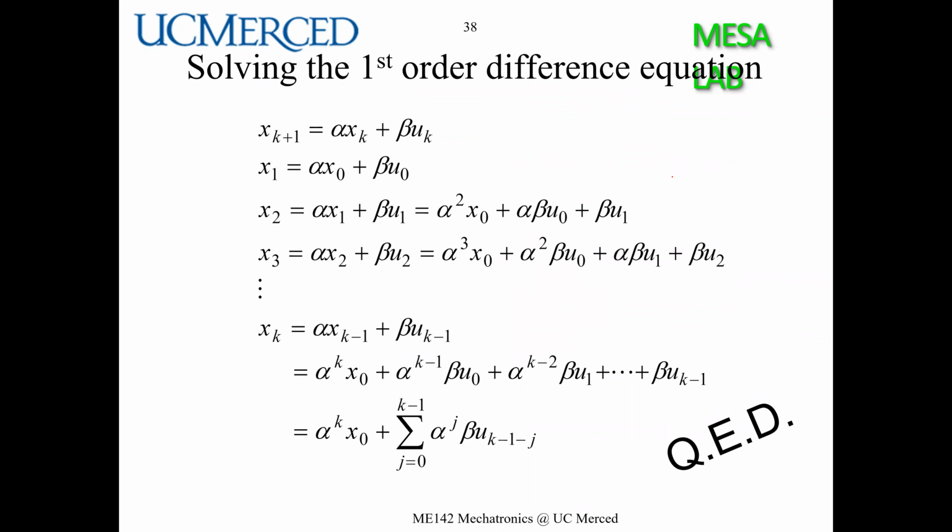So then we can do iteration, solve the first order difference equation. And this is called brute force recursive. You just derive from 0. But in the end, you can see this x k is linked to the external driving function, the driving control. This is the initial condition, so this is the initial response due to the initial condition. This is called ZI, zero input.